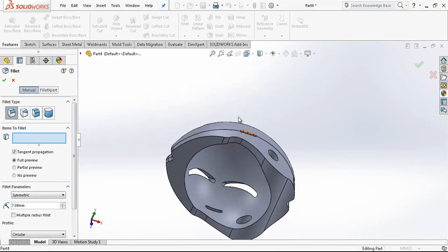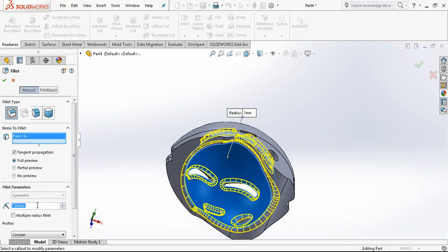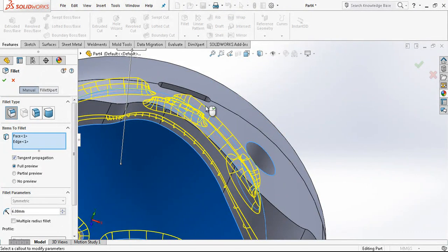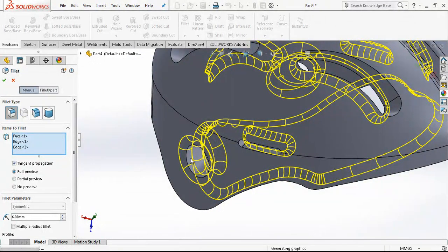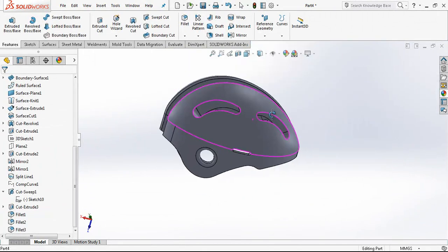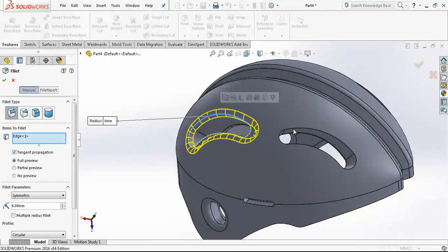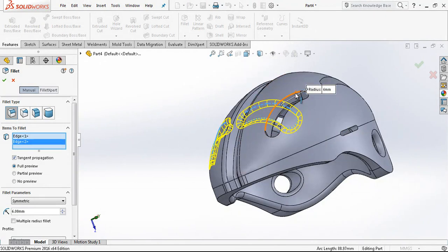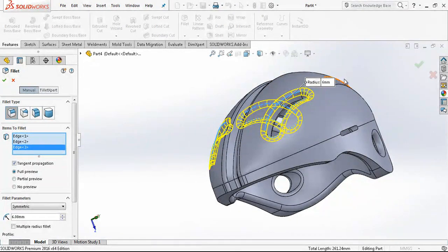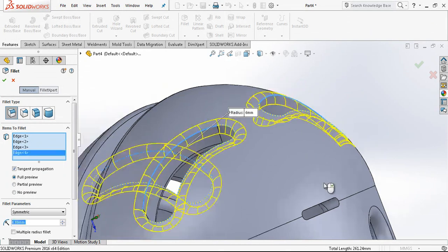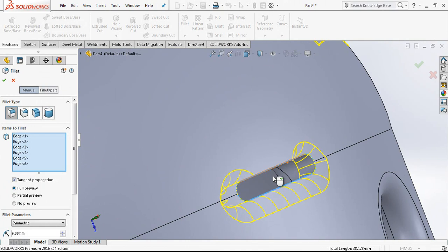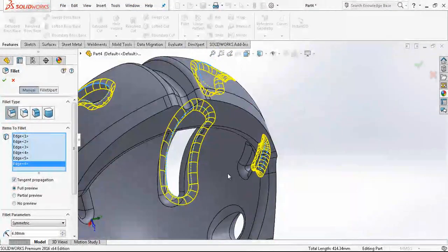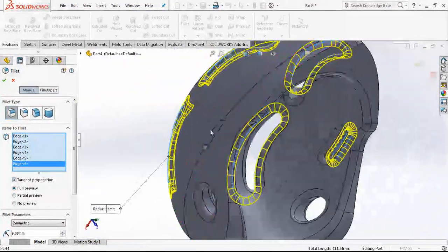Now by clicking inner face, I'm adding everywhere 6mm radius value. Here everything done, and I'm going to add here my radius again by clicking simply corners, and we are going to add also here radius, which is added by clicking surface inside before.